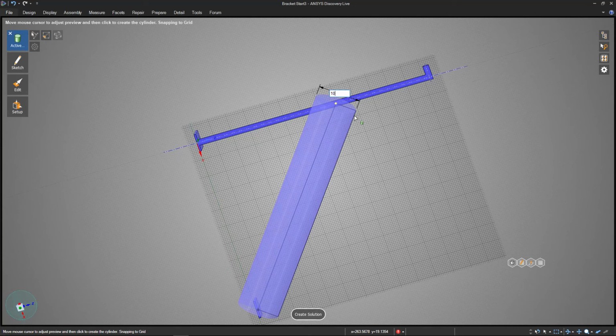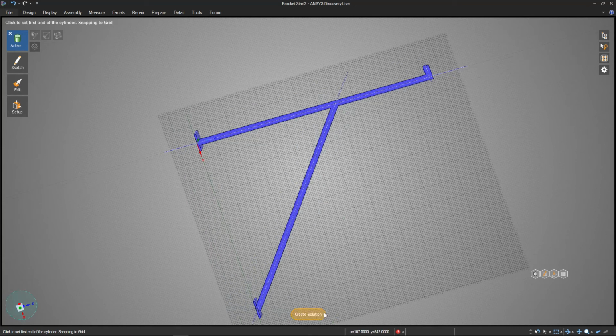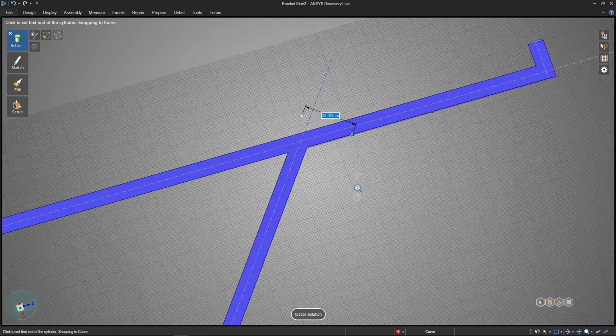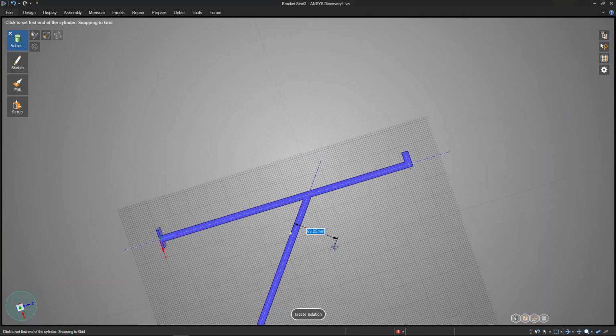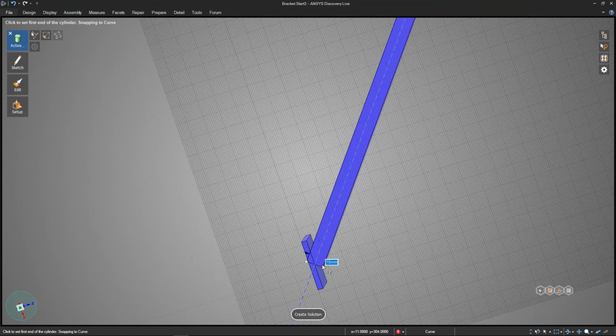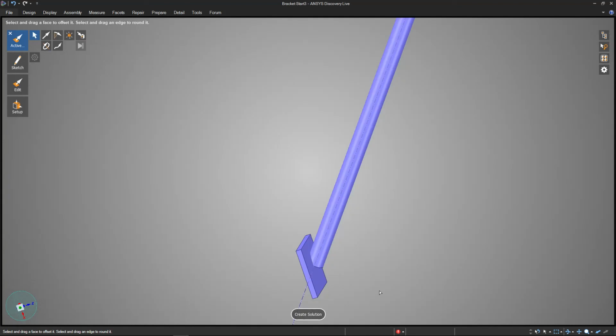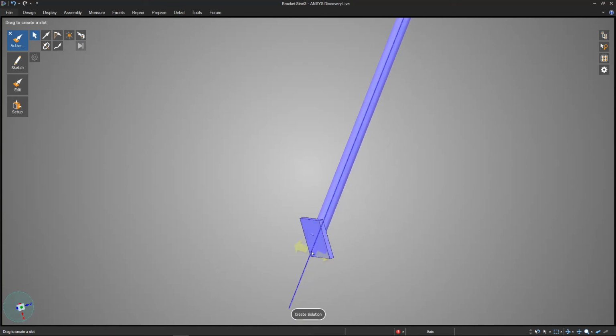The final click determines the diameter. I'm going to enter that as 10. So looking good up here, it kind of made it all one shape, but you'll notice something down lower that is going to need our attention. It doesn't seem to have combined these quite like we might want them, and as I exit the sketch mode and go to 3D mode, we can even see that it is protruding out of the back here a little bit.